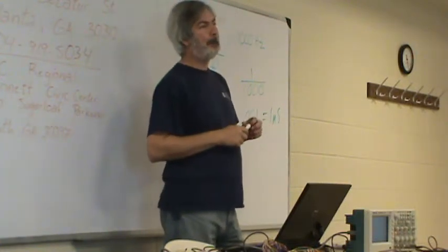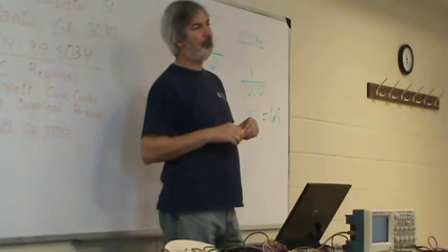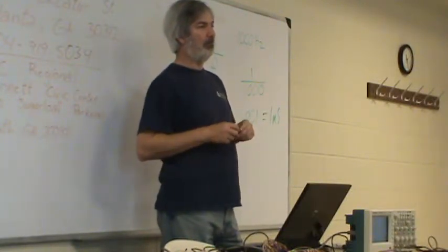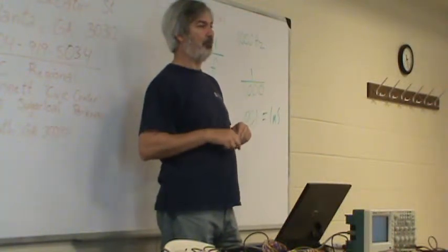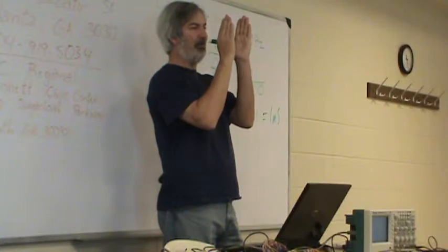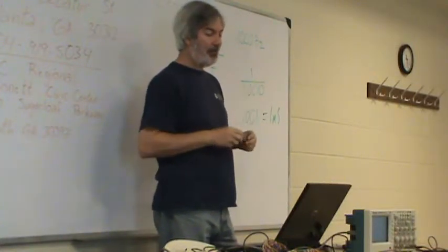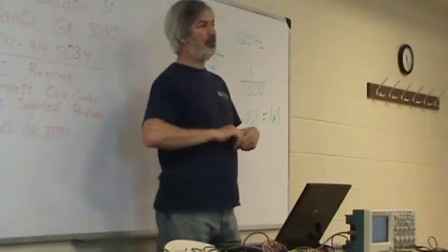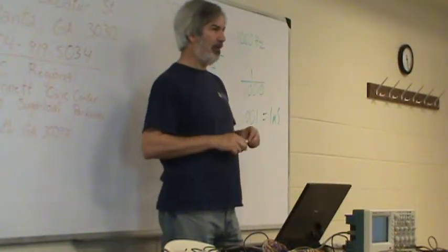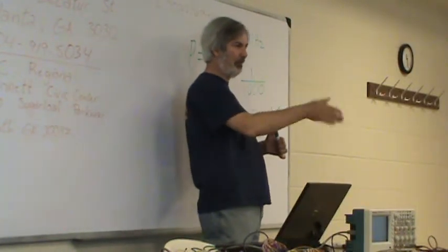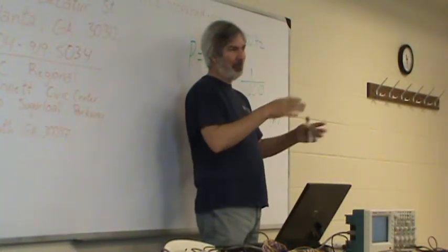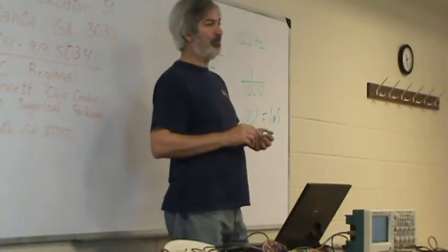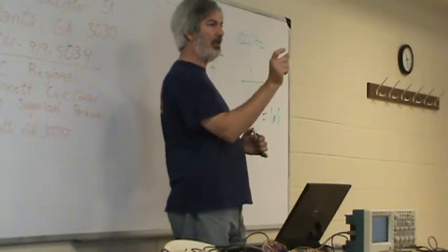What's the disadvantage of setting the scope up so that you're always at a very fine, a very high sample rate? There's got to be a disadvantage to that, right? Oh, absolutely. Your screen ends up showing such a small part of the signal that it doesn't make sense. Oh, okay. With scopes, even with the digital scopes, you don't actually directly set the sample rate. You don't set that clock that it takes samples with, although internally, the scope may change that depending on what your other settings are. What you'll actually do is set the speed of the scope as the period per division on the screen.